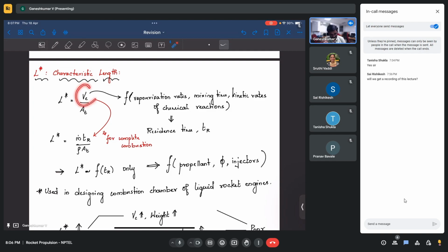That is why your chamber volume design is going to depend on all these three things. And actually, these three things are coupled. While evaporation happens, once it evaporates, the fuel and the oxidizer come out, and then it starts reacting and puts a flame here. This is how it ideally happens within the liquid propellant rocket. There will be a droplet, and above that there will be a flame. So all these three things are coupled to each other.